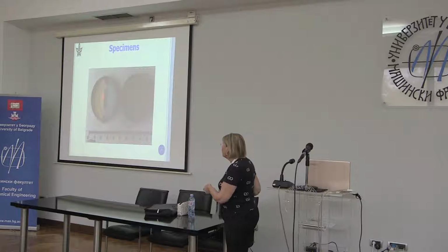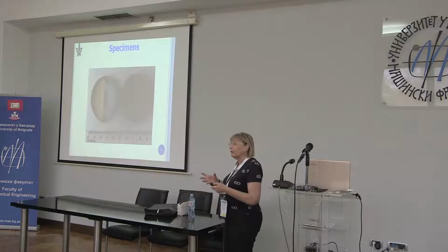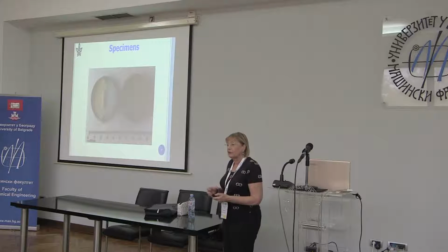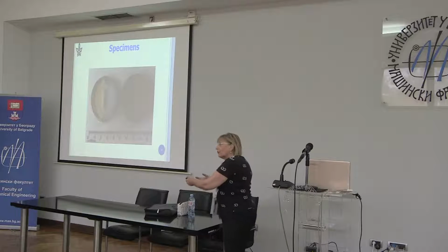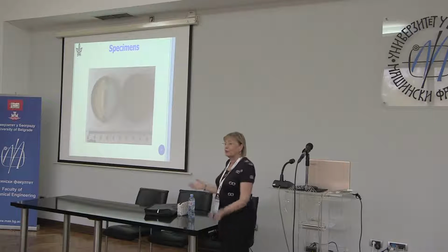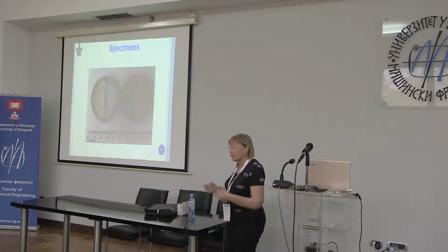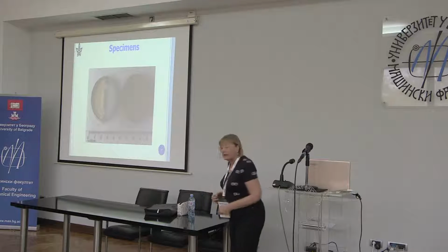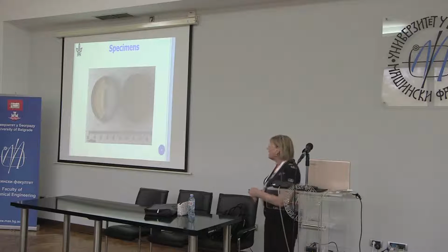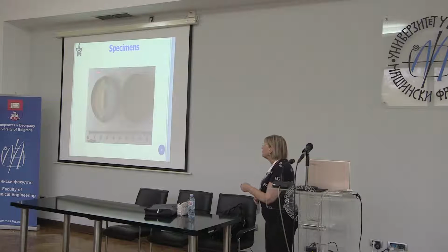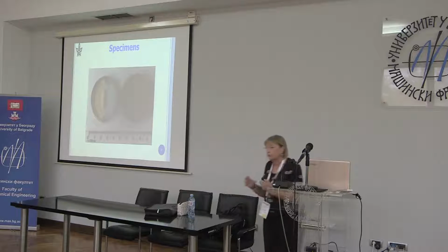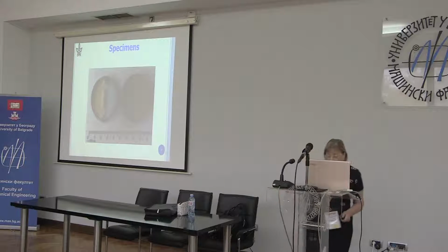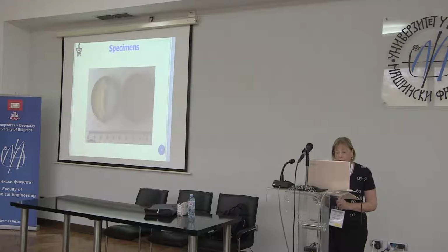We have all of them cracked here, because the temperature in the lab went down to like 16 degrees Celsius at night, and we came back in the morning, put on the heat, and we went up to 22 degrees, and that was enough to crack the specimens. In fact, by the time morning came, without putting on any heat, it was warm enough in the lab to develop cracking here. So the aluminum, we came up with that. Fortunately, aluminum and glass have very similar Young's moduli, so that is what kept the specimens together. So those are Brazilian disc specimens.